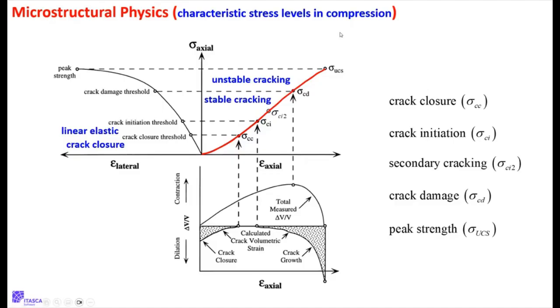And this is because this peak stress is a function of all this crazy damage going on. When it's elastic, there pretty much doesn't matter, little tiny variations. But those 30 samples, if you did microstructural scans, are not 100% exactly the same. And this UCS is going to be sensitive to that sort of stuff. But it's the best we can do. So we do this, we measure this.